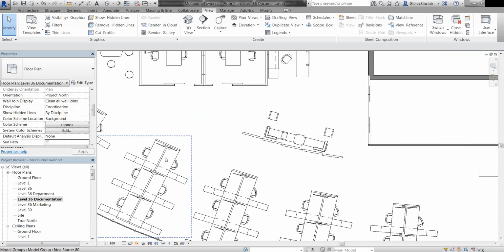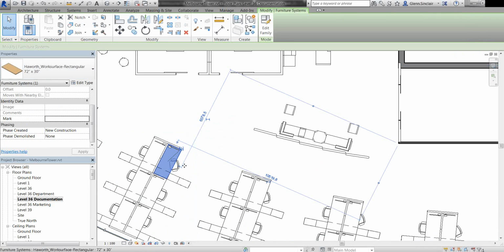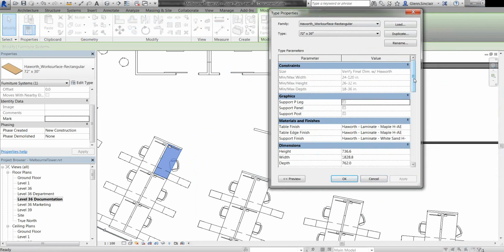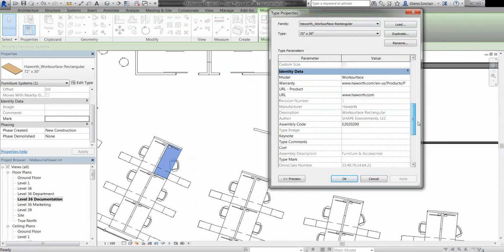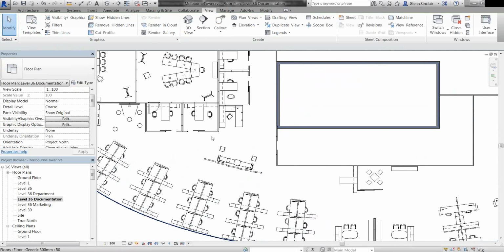So rather than, again, typing notes in, what we do in a Revit context is use the information contained within the objects. So within the 3D object there is a bunch of information, and the one that we might be interested in is, say, the assembly code there to show up on our floor plan to identify which piece of furniture is which.